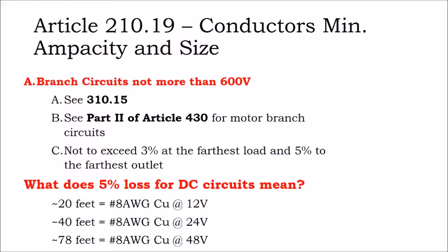Well, in the solar industry, we're usually designing for a 2% voltage drop or less. So we're upsizing our cables for voltage drop, and we would not violate this code. And, you know, it's usually cost effective to spend a little bit more money on cable and make it up in efficiency gain. So, yeah, not trying to get the 5%, but going for a 2% is kind of the more sane, rational approach.